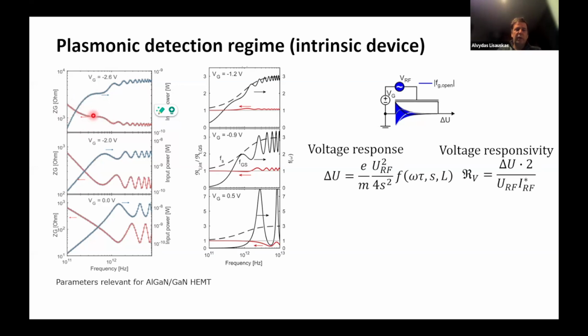On a frequency axis at different gate bias points, one would find out that the impedance changes a lot. And at gate bias equals 0, for example, here it gets really pronounced waves. So this is where one definitely expects to see, okay, it is in a few terahertz frequency range, so not that practical, but for simulation, one definitely would expect to see a standing wave happening in a channel. So these plasmons were first of all not predicted, but outlined.